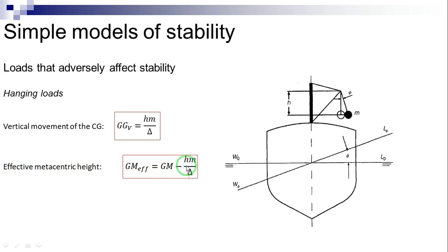Lifting of a weight W, in addition to modifying the vertical center of gravity, generates a transverse heeling arm as shown here. Here D is the transverse distance from the center line to the end of the boom.